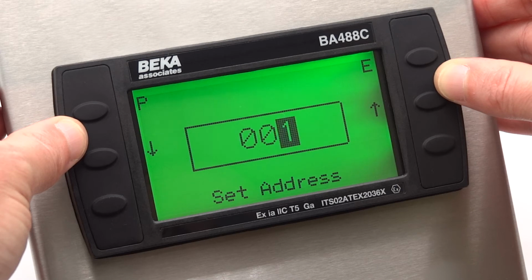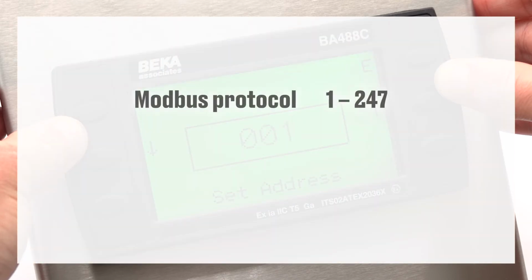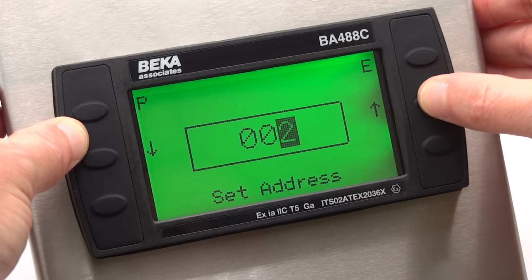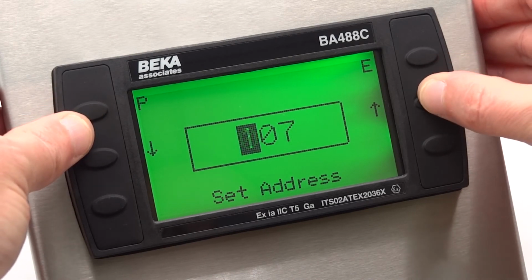Each text display must be allocated a unique address, and here is where you do just that. The range of the address depends on which protocol you have selected, but for Modbus it can be any number between 1 and 247. Modbus 1 to 247, BEKA 0 to 247, Legacy 1 to 15. Once the correct address has been entered, come back out to the comms menu.